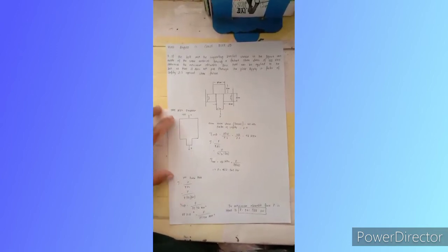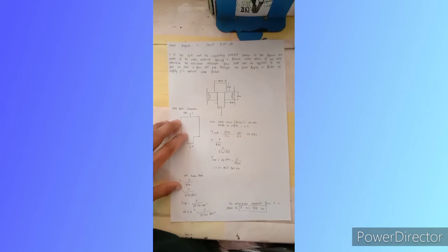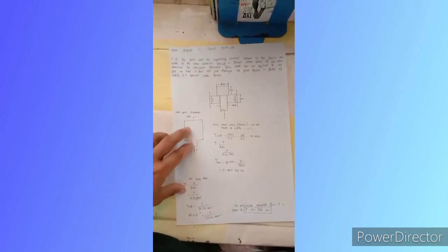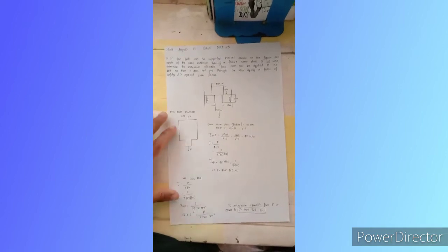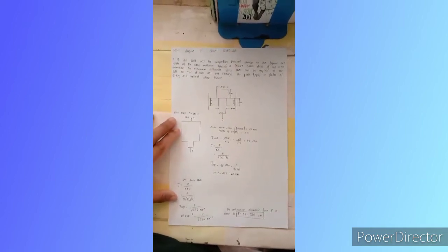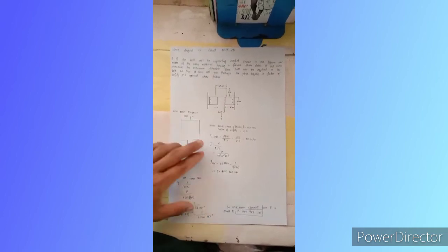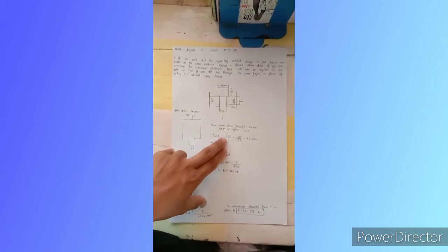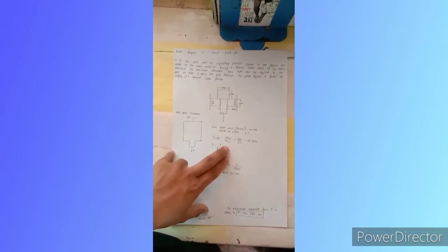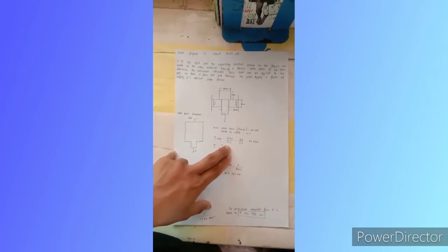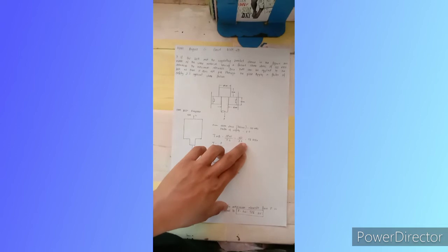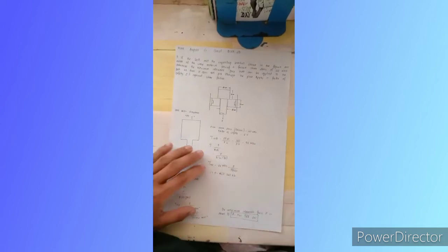So, in our free body diagram, FBD, we have a vertical V and P. Given the shear stress failure of 120 megapascal and the factor of safety of 2.5, shear stress safe is equals to stress fail all over factor of safety is equals to 120 all over 2.5 is equals to 48 megapascal.